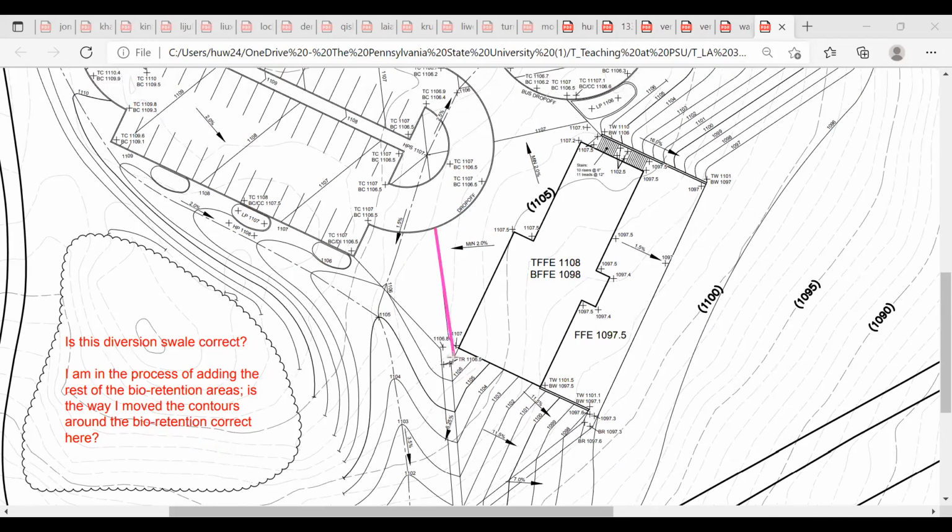So that 7 goes here, right? That means your elevation here is 7. So your 6 would be a little bit lower, not too much. And then it goes like that. Your 6 wouldn't be here because I don't think you have 50 feet. I think your 6 will be entirely low, entirely down, even like this, because now we're creating a swale that we want to go this way. Okay, that is your retention.